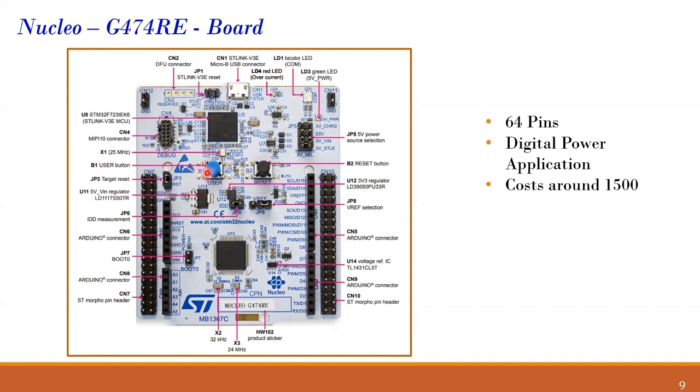So if I click this button, then it is interfaced to one of the pins of the microcontroller, and it will generate an interrupt or something. And there I can write some events that if the button is pushed once, then you must change the frequency. Or if the button is pushed 3 times in 1 second, that means you have to stop the PWM signal, etc. Like that, we can configure it and we can define certain events based on the push button.